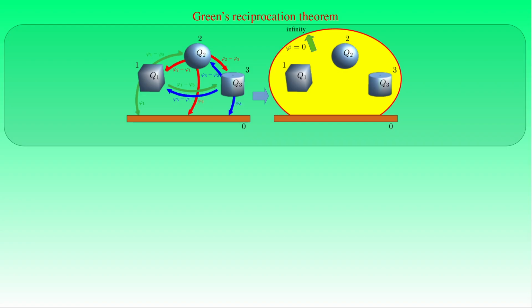Therefore, any imaginary equipotential surface S0 of zero charge and zero potential at infinity joined with the earth or the electrode 0 can be considered as an uncharged conducting surface that encloses the system of charged conductors. The union S of the conductive surface S0 and the boundary surfaces of the electrodes 1, 2, and so on, denoted by S1, S2 and so on, forms a boundary of the volume V enclosing the region of the system of electrodes but excluding the electrodes themselves.